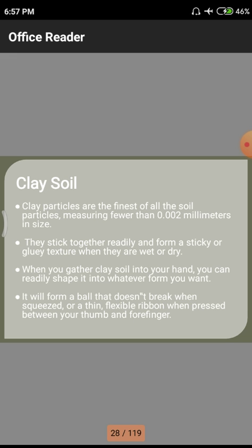Likewise, in clay soils, sandy soils and other soils, we have different particle binding properties because of particle sizes and their chemical properties. That means chemical properties measure what amount of different chemicals is present in the particular soils, so there will definitely be a change in the different chemicals. Normally in silty soils we have more silica, but in clay soils we have more ferrite and other montmorillonite-like chemicals, so there will be a huge amount of binding properties in the clay soils.